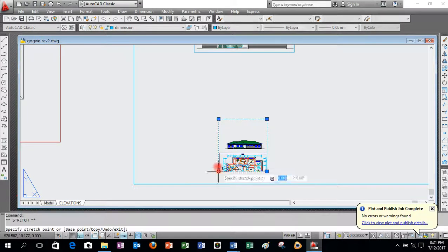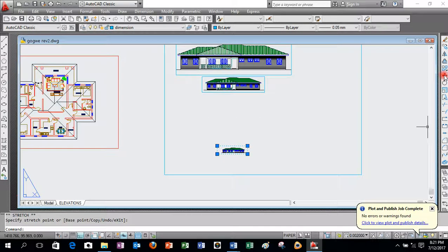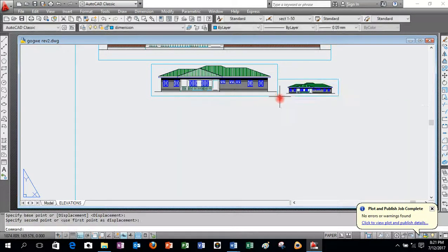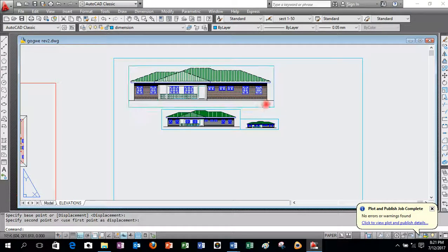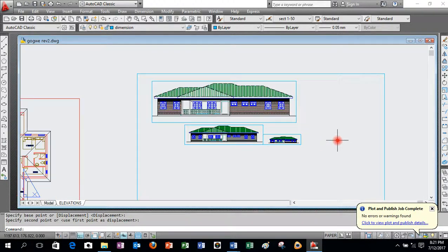But where you need to print several drawings, it means that you'll be selecting, the way I'm doing this, the drawings that you want to be printed. So you see that if we move this, we have this can even come there. If we move that from that corner to, yeah. So that you see that this is to a scale of 1 to 100, and this is to a scale of 1 to 200, and this is to a scale of 1 to 500. But all these drawings are the same. It's from the same drawing. So you can print one drawing several times with different scales.